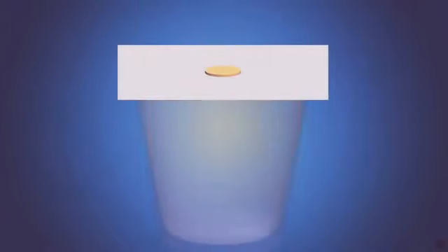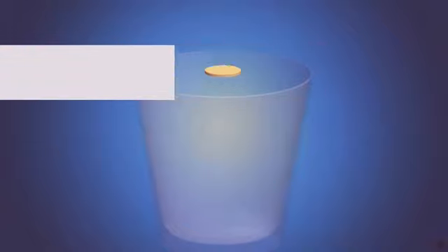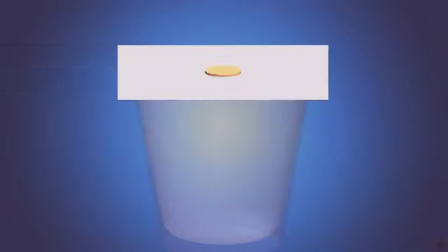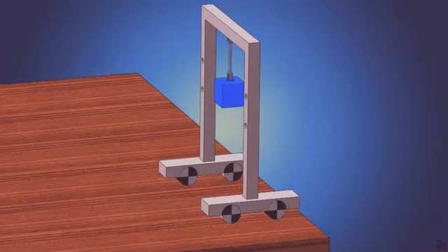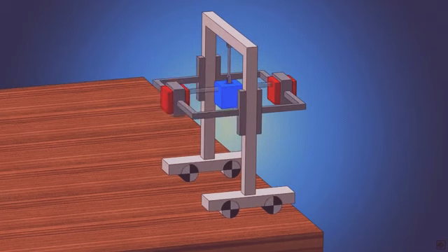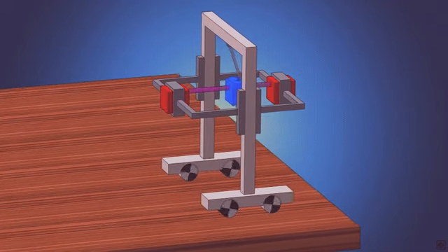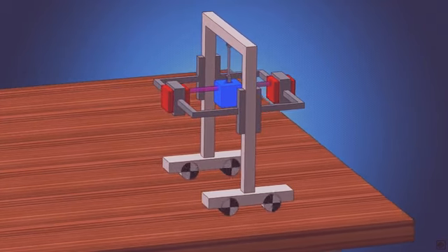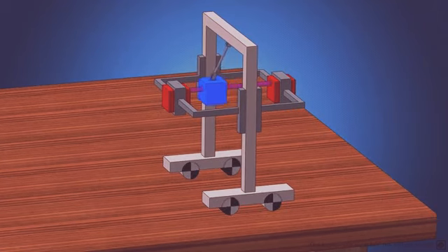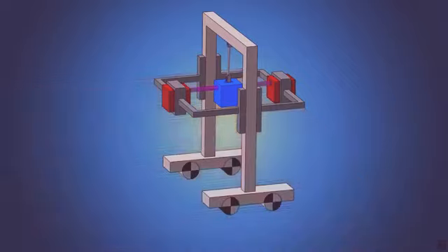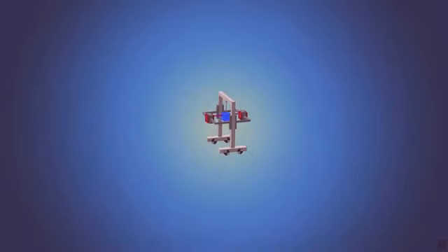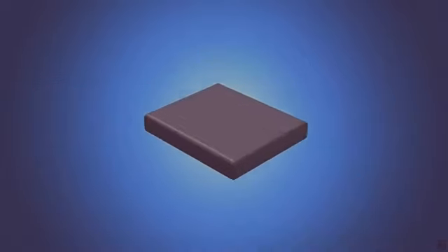But, how does an accelerometer work? It works on the principle of inertia, that is, the tendency of the body to resist change in its state of rest or motion. In this arrangement, a mass is suspended by a string. Now if we place two sensors that detect the distance to the mass, we can detect the deflections of the mass as the frame moves. But this is pretty big for your phones. So we shrink it down to the microscale, to make this tiny device called an accelerometer.